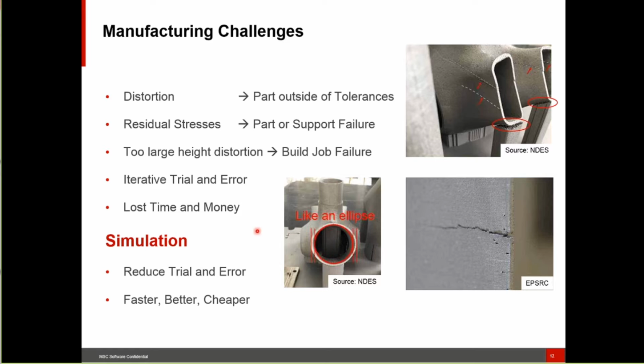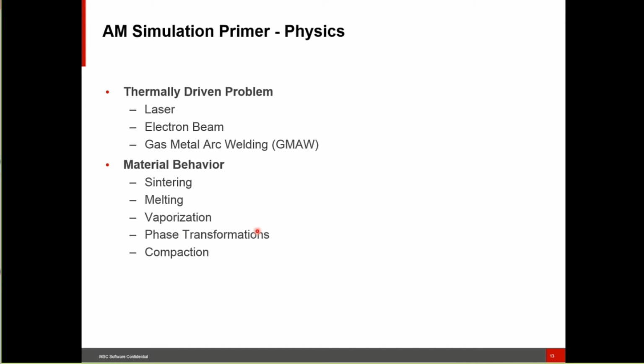That we can use simulation so that we can get to better designs that you put into the machine such that your net shape is the desired shape, that you don't have the residual stresses that might cause cracking in the structure, that you can investigate the residual stresses not only of the building up of these powder layers, but also the thermal process, the heat treatment process, the cooling process, the HIP process in the simulation.